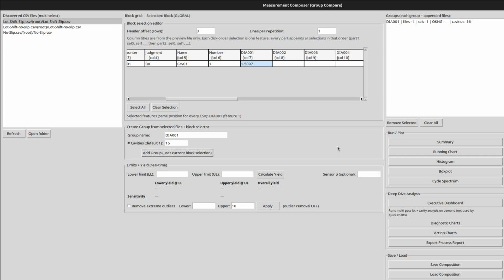So we're maybe skipping every 15th part or every 100th part, and that throws off our cycle so that a naive assignment of 1, 2, 3, 4, 5, 6, 7, 8, 9, 10, 11, 12, 13, 14, 15, 16, 1, 2. When you do that process, you start getting misalignments between the actual cavity data and your assumed cavity data, which introduces its own misalignment to what you would expect your cavities to be.